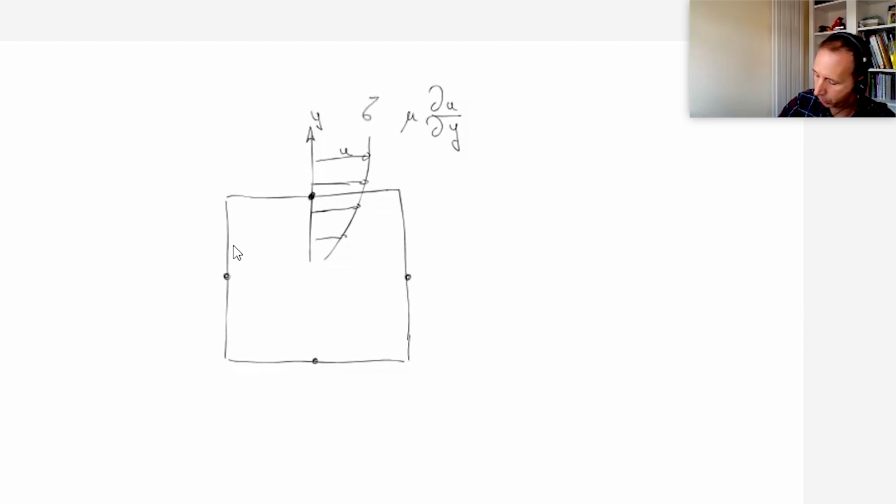The shear stress is going to be written tau yx, which means tau is used to mean shear stress in the direction perpendicular to y and in the x direction. So you end up with two definitions of direction. In 2D, it doesn't matter. Essentially, we will have a shear stress at that point along this direction. But in 3D, you have to define two directions in order to define a plane of stress, where the stress is being applied, and the direction in which it is going to be felt. So you define the plane and the direction. That's why you need these two components.